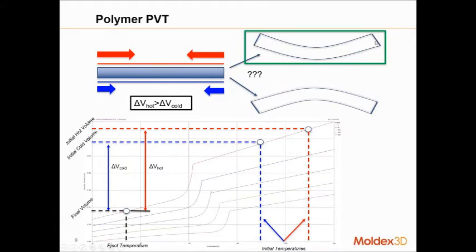So that's how we use this PVT relationship, and that's really where the philosophy comes from: being able to predict where the highest shrinkage material is going to be, where the lowest shrinkage material is going to be, and what are ultimately the differences in volumetric shrinkage, which is going to cause the warpage. Now, in this case, we just looked at surface temperature, which means that we were just looking at the skin. We could also do the same thing with the core temperature as well. If I were to look at something like a filling result, or more importantly, a packing result, because that's a little bit further on in the cycle, I could look at the core temperature and see what this effect would look like as well.